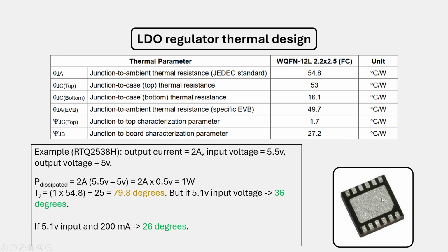Now, when you put it on the PCB, you connect it to the huge ground plane that you already have through lots of thermal vias down to it, and it will transfer the heat efficiently to the ground itself, which will act as a heatsink. And that is a very important feature of such packages.